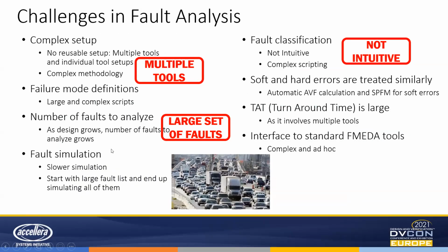So what are the challenges in this fault analysis? It's a very complex setup. Multiple tools are supposed to be used, which is what the Accellera paper also touches on. And failure mode definitions use large and complex scripts. The number of faults to analyze is very large, and as the design grows, the number of faults to analyze also grows. And fault simulation, with the current technology and algorithms that are implemented, is very slow. It starts with a large fault list and ends up simulating all of them. So there is no concept of taking only the relevant faults and moving ahead.